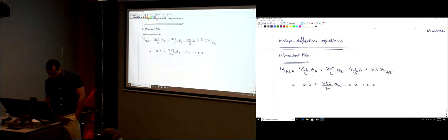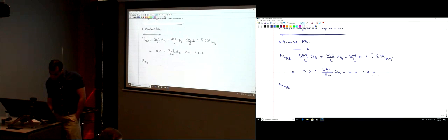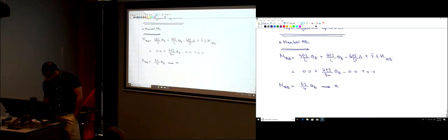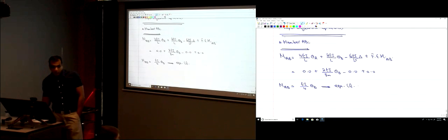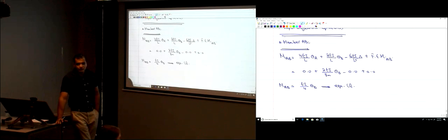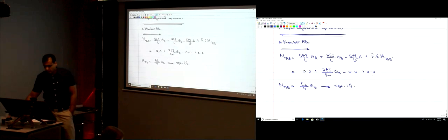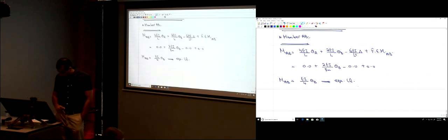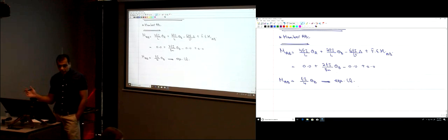So simply here, MAB, the moment at point A, is EI divided by 4 multiplied by theta B. Just going to name this equation 1. Okay? Why? Because we cannot use this equation without knowing how much is theta B. I need to know how much is theta B. Once I know theta B, I can find the moment at point A. Right? Now, let's write the slope deflection equation at the right side of member AB, which is MBA, the moment at point B. How much is that?